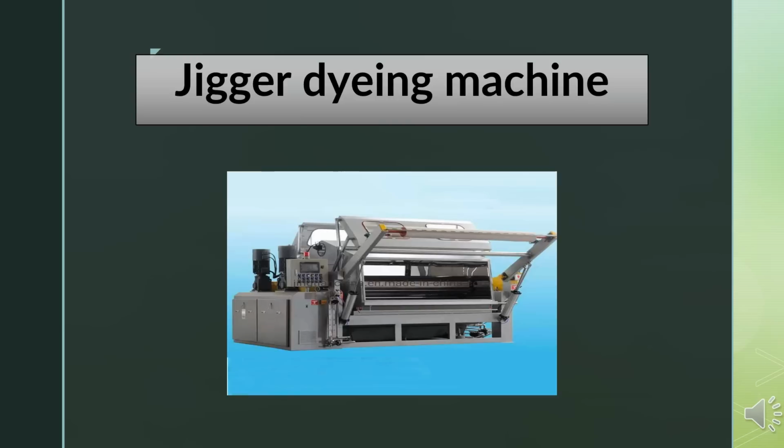One is that the fabric is pulled from one roll to another, thereby making it obvious that very fine, thin and weak fabrics may not be suitable for the process. Also, it is an open machine, so we cannot increase the pressure and hence the dyeing temperature above the boiling point of water. This restricts us from dyeing synthetic fibers in this process.